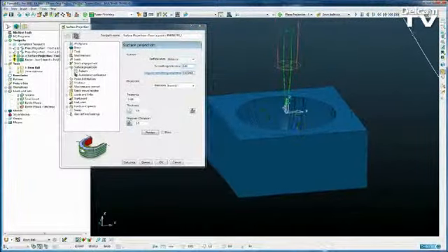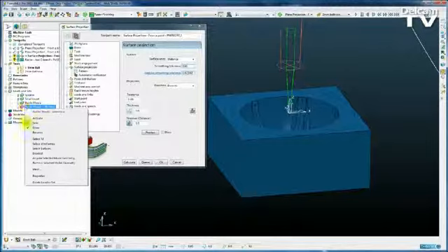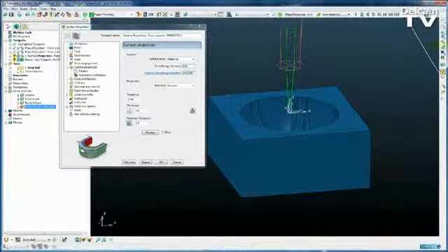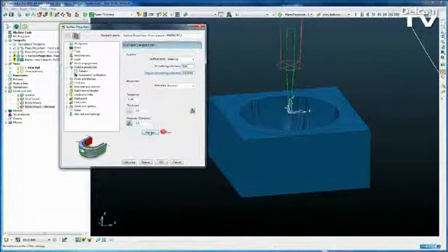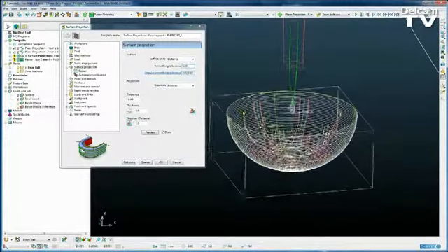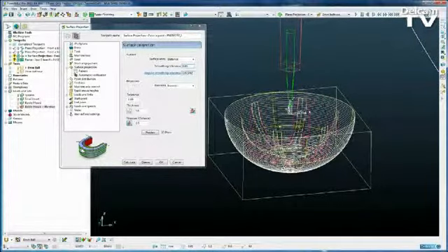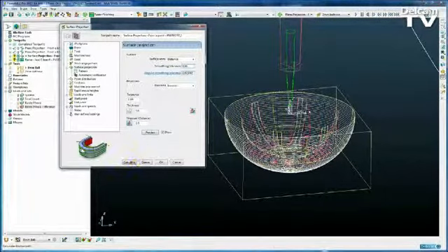And again, first of all, we'll create the toolpath using the previous functionality in PowerMILL 2012. So all the settings are correct. If I draw the preview frame, so there we can see the preview frame for the surface projection, and as I've just explained in the previous toolpath, the tool axis is applied to this preview frame and then projected onto the part. So the tool axis is correct before projection, but after projection the tool axis then is incorrect.